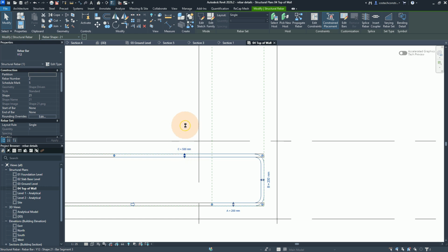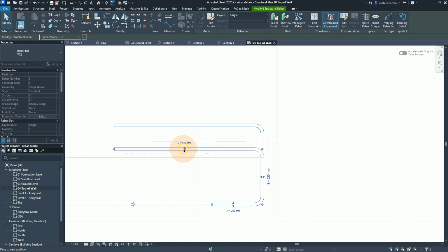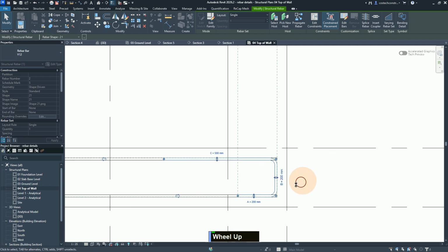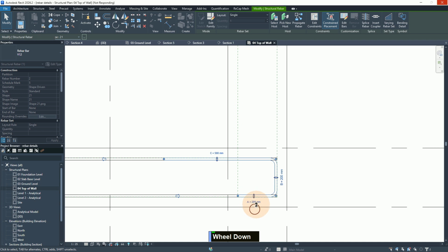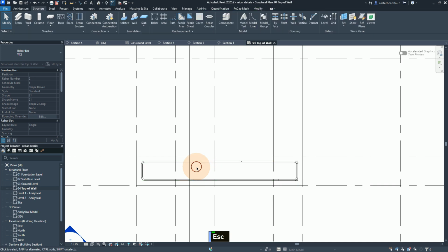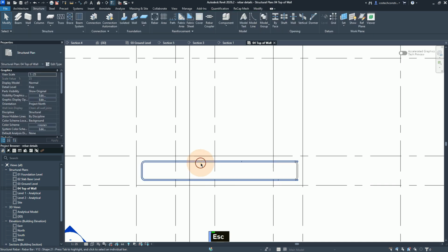And now if we move it above, then if we now select it again, if we take it up to here, it will automatically be snapped to the cover. Now notice that this side the A is below here. And if I press escape, then select this other Rebar set, the A is above.